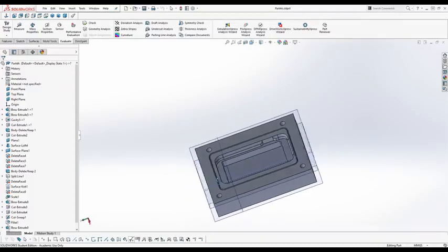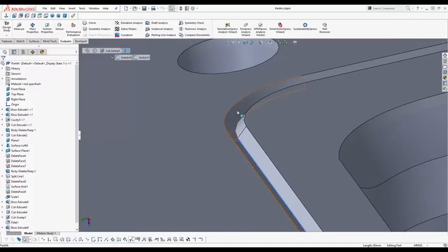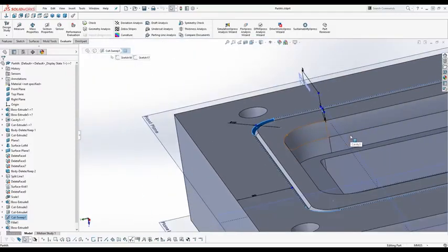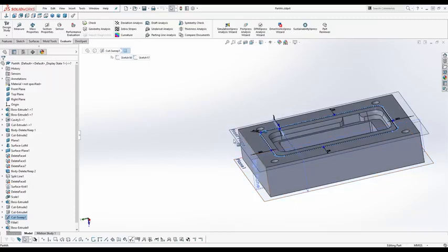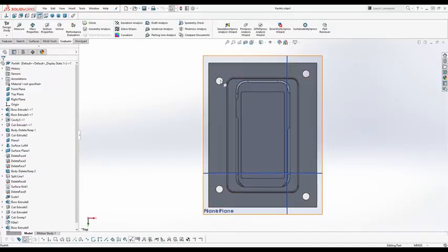Another feature is a lip and groove on the mold. This is the groove, and the other side of the mold has the lip. With this you make sure that your mold halves accurately fit together so that they cannot move from each other. There are also 4 mounting holes. These are for 4 bolts to clamp the mold together, otherwise you have the possibility of plastic flowing outside of the cavity and in between the 2 mold halves. As you can see, I placed the mounting holes asymmetrically so that it's not possible to flip one of the mold halves and connect it in the wrong way.